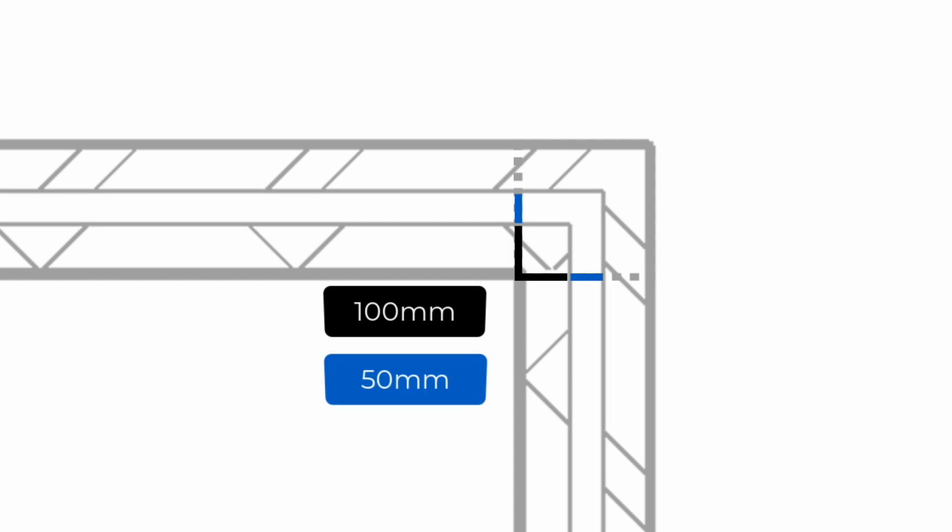Okay, so now we know where the extra distances come from, how do we calculate what these distances are? To do this, we need to look carefully at our corner. We can easily calculate the length and width of each corner by knowing the widths of each skin. For blockwork it's 100 mm, for a cavity, in this case 50 mm, and for brickwork it's 102.5 mm.